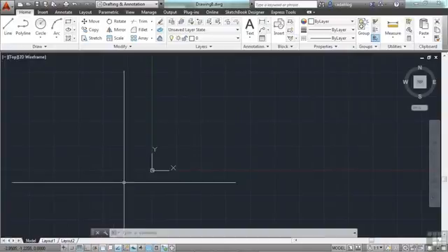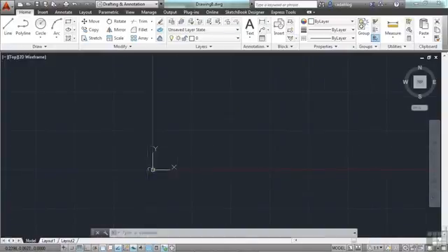There is a third axis, that's the Z axis. That's where that little square comes in. It sticks right out at you, comes right out of your screen. Now this axis isn't really accessible in AutoCAD LT, but if you're using AutoCAD LT and you open up a drawing that was made in regular AutoCAD and that file has objects drawn in it, they're there. It's just going to be a little tricky to access them, so just be careful. The three axes together create a 3D grid. In AutoCAD LT, there's just a 2D grid.